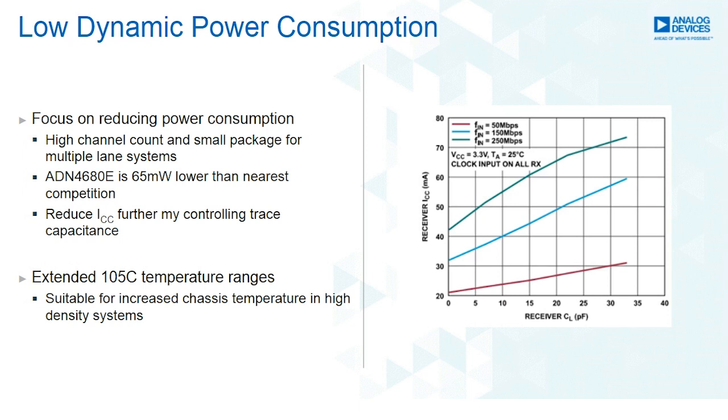The circuit here is a SPI over M-LVDS with a little more technical detail than before, using 2 ADN4680Es, one at each end of the SPI. So the way it's set up here, an I/O pin can select the transceiver to operate as either the controller or the peripheral role in the SPI. The IEC ESD protection of the transceiver is a nice feature when you're extending SPI over long distances, where EMC and transients become a bit more important.